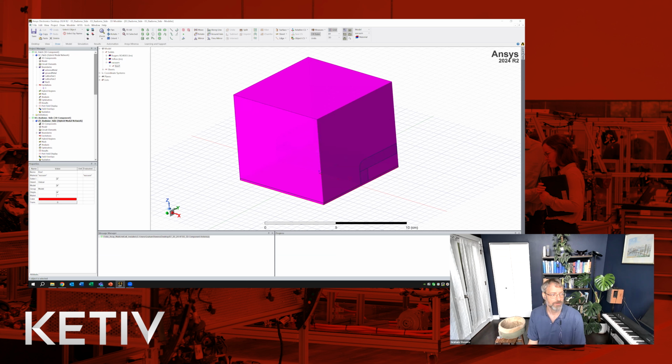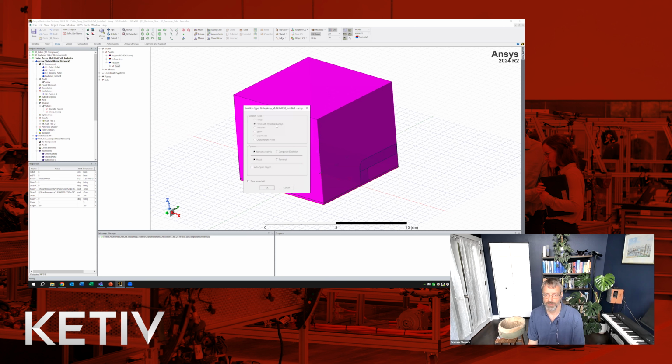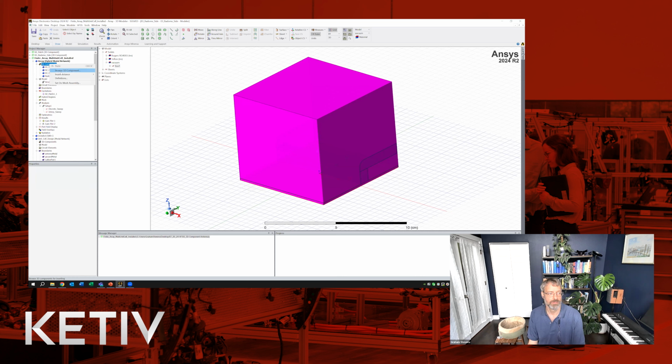And then once we have all those 3D components, and we're now wanting to put them together in an array, you come to a blank HFSS hybrid modal network here. So with hybrids and arrays, it's important. And then right-click on 3D component, and you would browse 3D components, browse for those 3D component files you've already saved, and then add them to the model here. And so this one has 4 different components listed.